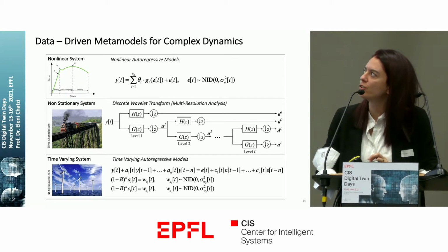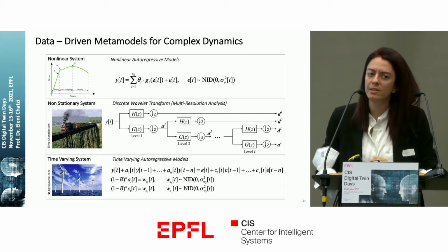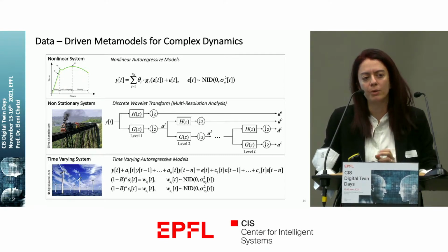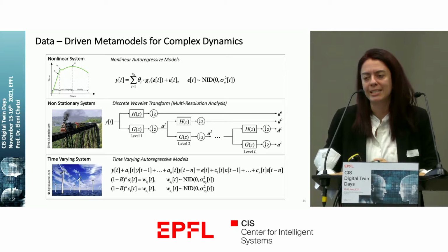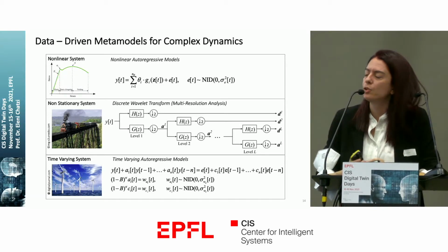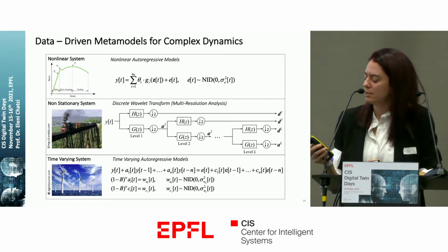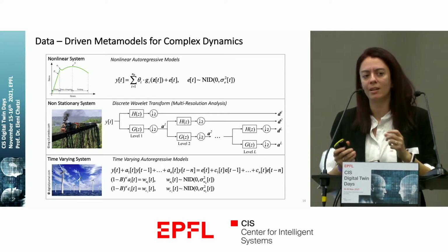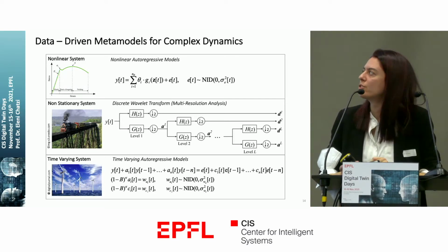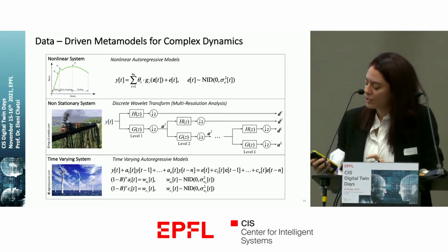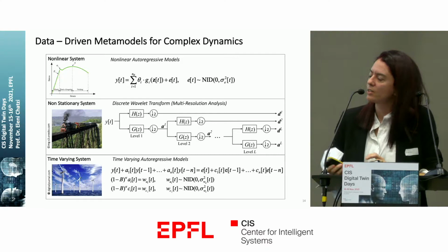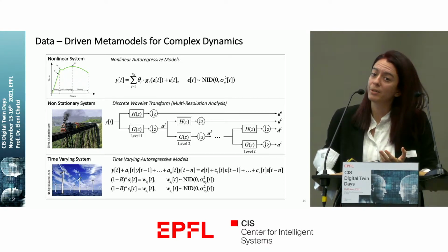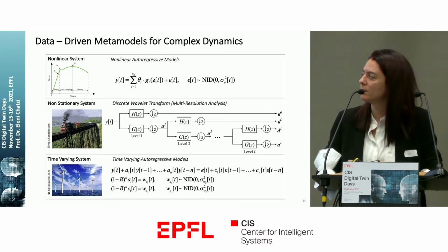Again, here is your chance to introduce structure into the system. So if you know that you're dealing with models that are possibly nonlinear, maybe you have a structural system that is experiencing yielding or geometric nonlinearity because of large displacements, then there exists a class of parameterized models that can quite comprehensively account for such behavior. If the system is non-stationary, then you could use a discrete wavelet transform to achieve the same goal. You could have a parameterized model that can track this kind of dynamic system.